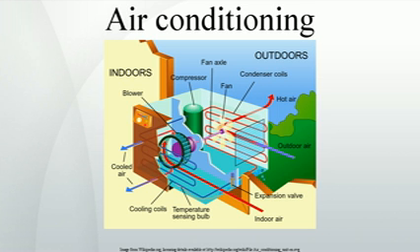A specific type of air conditioner that is used only for dehumidifying is called a dehumidifier. A dehumidifier is different from a regular air conditioner in that both the evaporator and condenser coils are placed in the same air path, and the entire unit is placed in the environment that is intended to be conditioned, in this case dehumidified, rather than requiring the condenser coil to be outdoors.